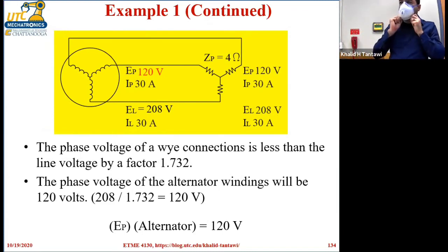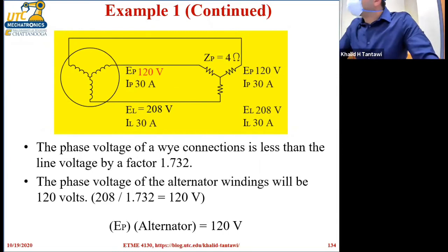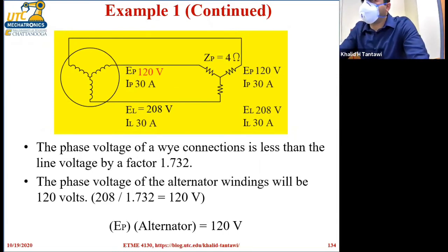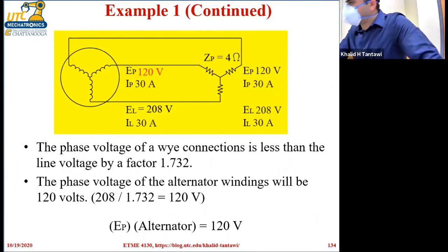All right. Now the question is, what is the power? What is the power equal to? Okay, this is a pure resistive load, so that means the kVAs are going to be equal to the kilowatts. Remember, the power per phase is I multiplied by V. How many phases do we have? There's 3. So you multiply 3 by I phase by V phase.